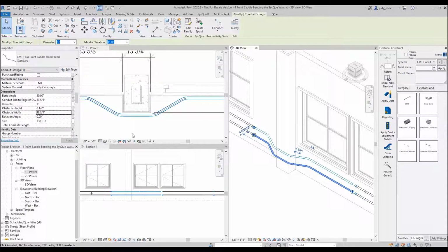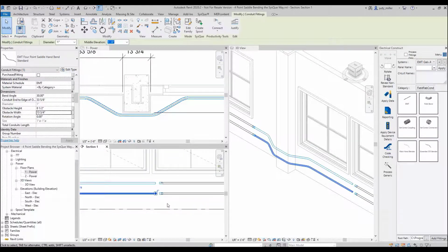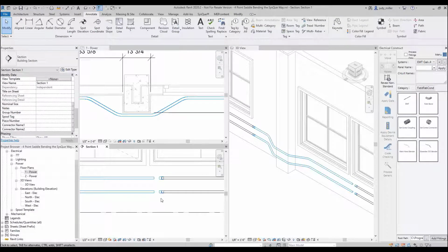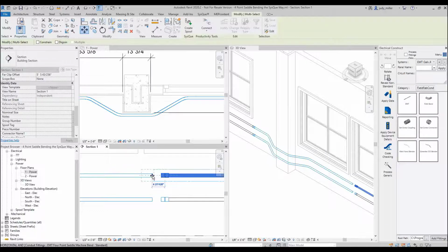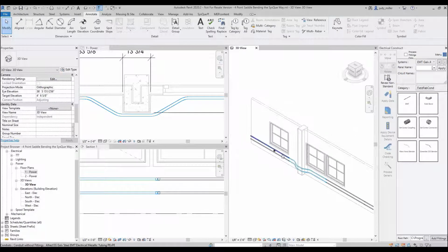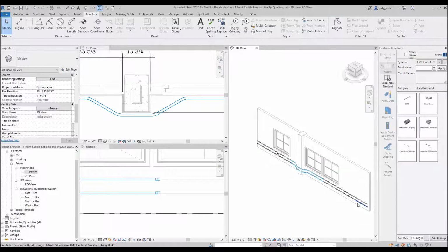So we're looking at it now in the plan view and in the ISO view. Notice, and it really shows in the front view, that our conduits, or our couplings, don't align to the couplings that were placed previously when the conduits ran right through the column. And that's because we took that 10-foot piece out, and with bending it, we have shrink in there. That's why you see a gap in there. So we would just simply take that conduit and move it into the end of our offset family. So now we have our conduit nicely going down the wall, around the columns, and continue on.